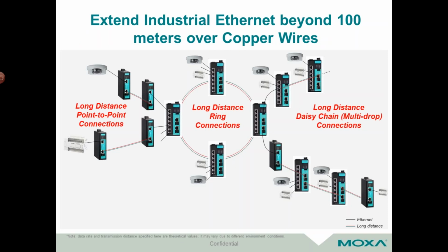The nice thing about DSL extenders as well is that they're extremely flexible in terms of what you can do with your topology and how far out from your main control center or main control room you can extend them. There are two main types of DSL extenders on the market. One is a standalone extender, and one has Ethernet ports built into it. The standalone DSL extenders typically take in Ethernet on one side and put out DSL on the other side. So they're useful for a onesie-twosie run off of a main control area.